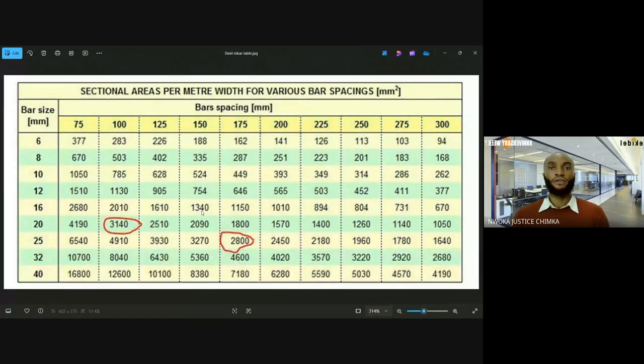You just look at your drawing. And if there's any mistake at site, let me say during the spacing of the reinforcement, instead of 175 they are doing 225, you might just say it's nice, ignore it, which might give issues. But if you're the one at site, you already know what made you go lower in spacing.